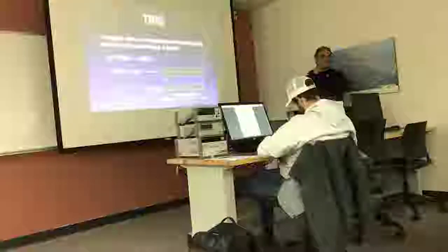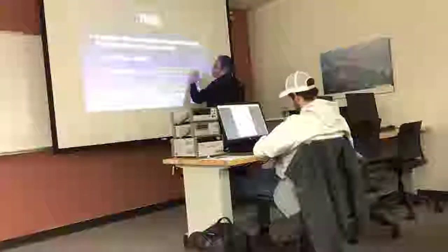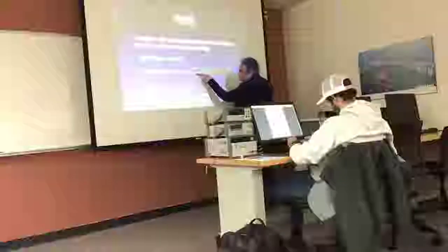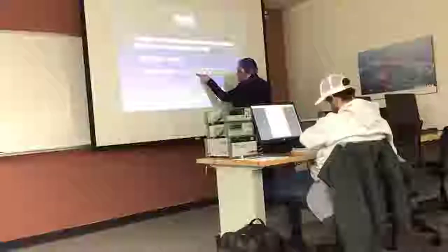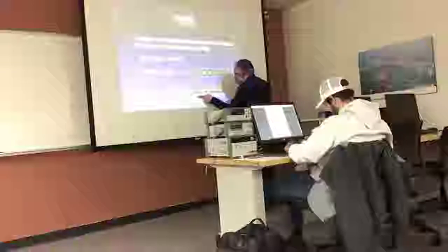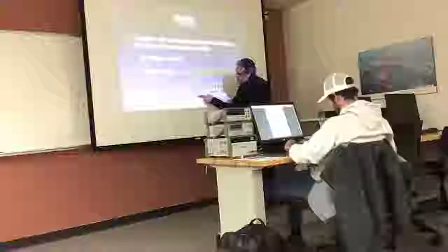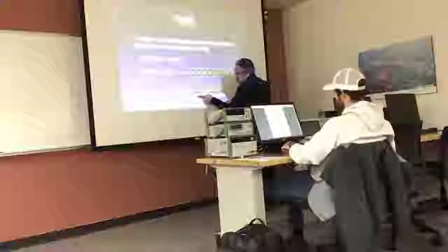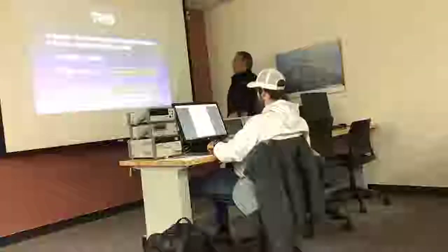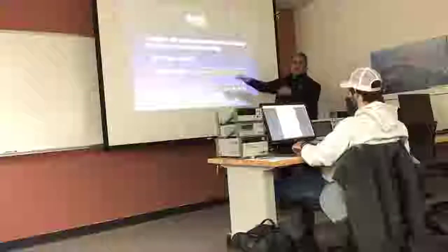See that? The same thing is happening on that 0. Now, I'm not talking about the guys in the middle because by explaining that 0, we know what the rest of the pins are doing. But the moment that that 0 lands in that position, it's going to force port A7, which is physical pin 13, to behave as an output. Will all of them be an output? Yep, all of them will be an output. I'm just showing you the corners, and then I'll let you figure out the middle.